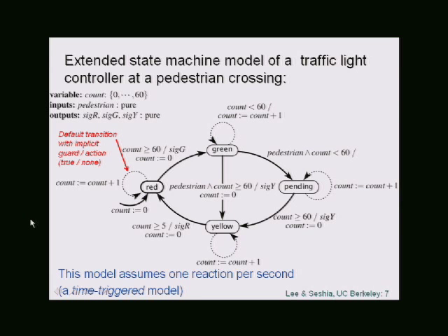And if you just check if the sensor value equals 0, for example, well, it may not be 0. It may be 0.001, and the equality won't hold, and therefore you will miss the condition, right? So oftentimes in embedded software, you will see that people don't actually use equality for guards. They use greater than or equal, or they may have an interval. So it might be if it's within a certain interval, 60 minus epsilon, 60 plus epsilon, then the transition is taken.